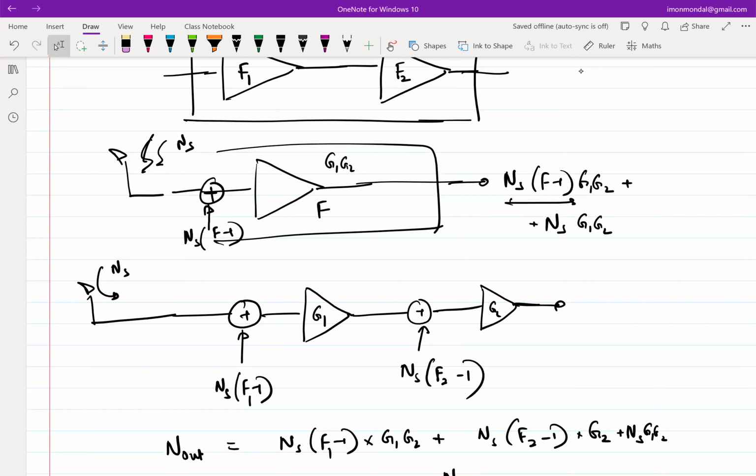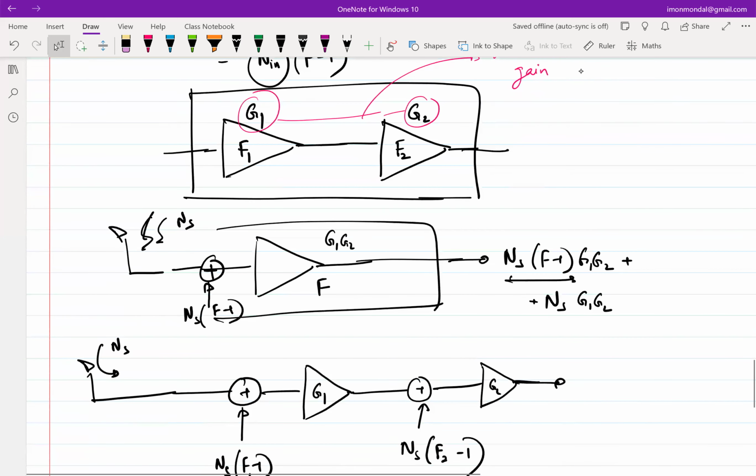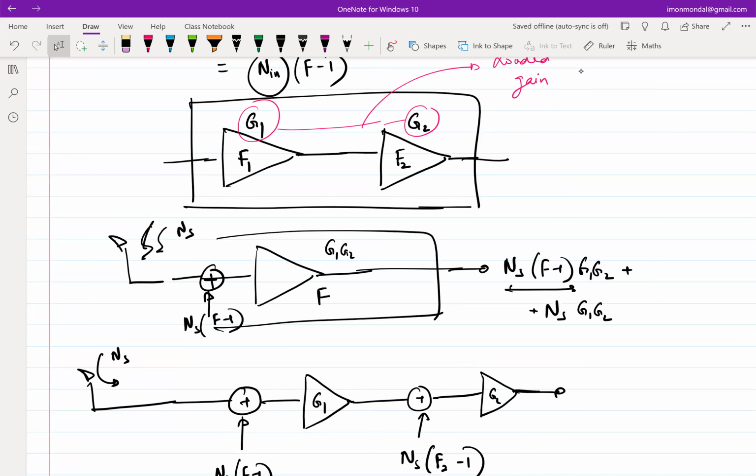Okay, so if I check the noise factor, what is the issue here? So we are standardizing with respect to some standard noise. Yeah, but the input noise can be from any. No, in this case, if you have to equate both these cases, I have to equate both these cases under the same condition. So the input noise has to be some NN, not equal to standard. Yeah, I agree.